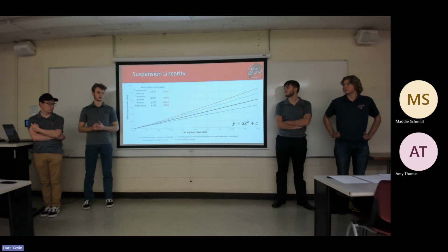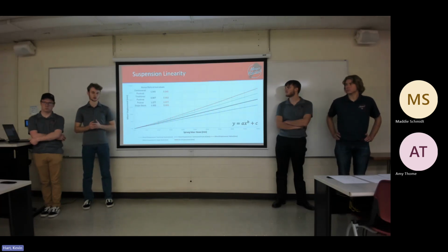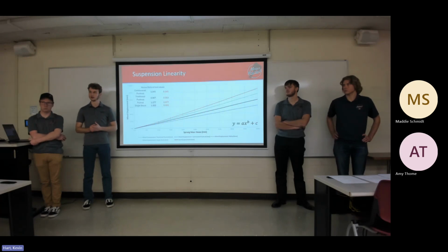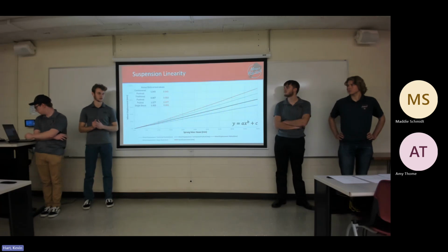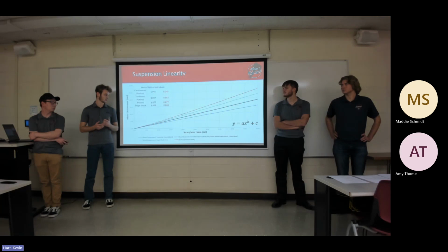And then we rated each of these based on their value and where they were farther or closer to a power value of 1. So for the values here greater than 1, those are progressive, being that the suspension will get slightly stiffer throughout the travel, and then this value below 1 is digressive, where the suspension will get slightly less stiff as the travel increases. And we rated these designs based off this.